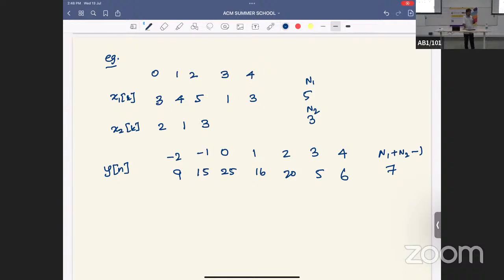Okay. Is it fine? Now this is for 1D, right? This kind of convolution is used for analyzing speech or ECG and those kinds of things. You need a 1D filter to move around. So what is the use of this filter, I will say. Normally we call the bigger one here the signal, or the data you want to process, and this is the filter coefficient.